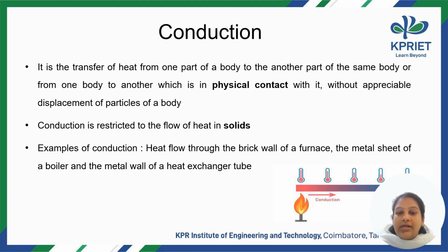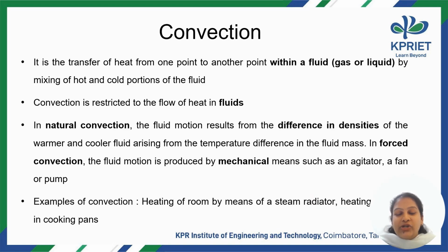So as the distance increases the temperature of the body reduces. So conduction is a mode of heat transfer that takes place from one part of the body to another part of the body, which are in physical contact with each other. And one of the important criteria is that both the bodies should not be in motion. So without appreciable displacement of particles of the body is an important criteria for conduction to take place, and conduction happens only in solids.